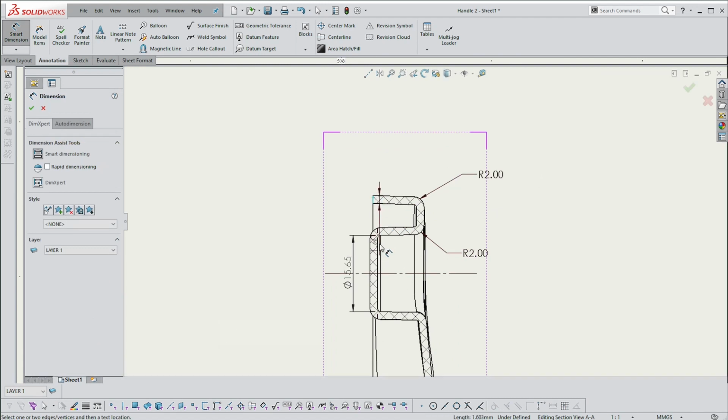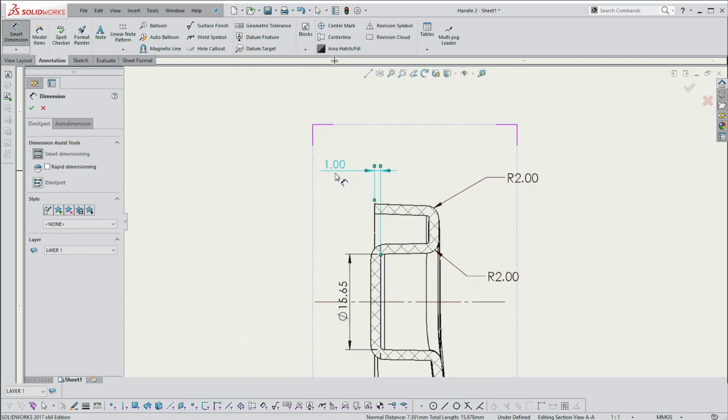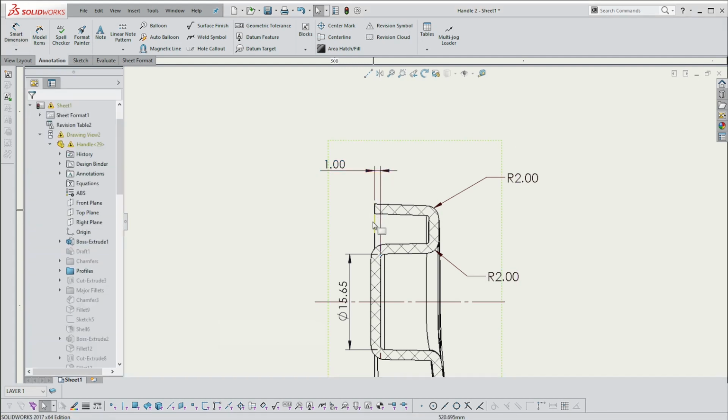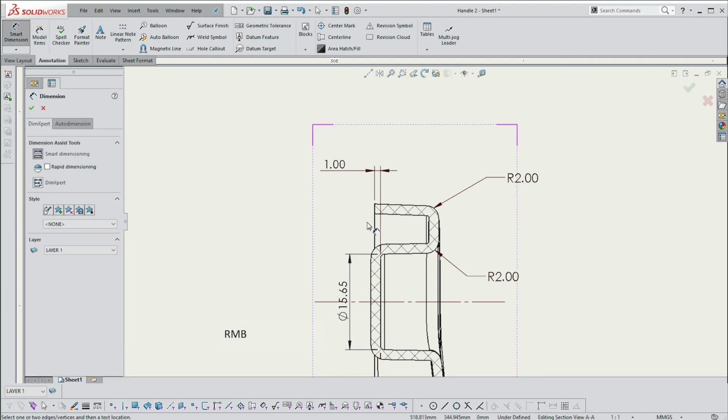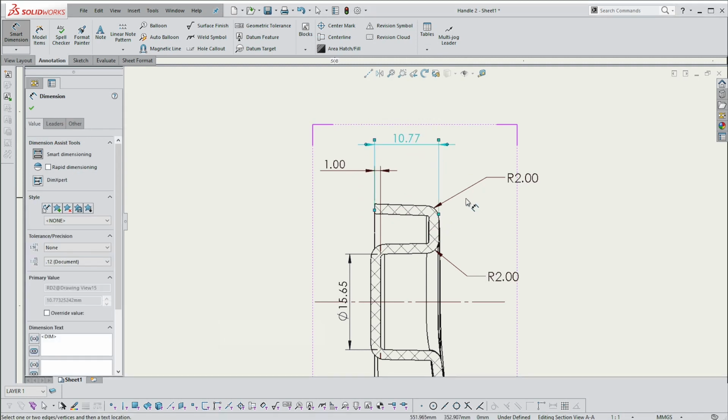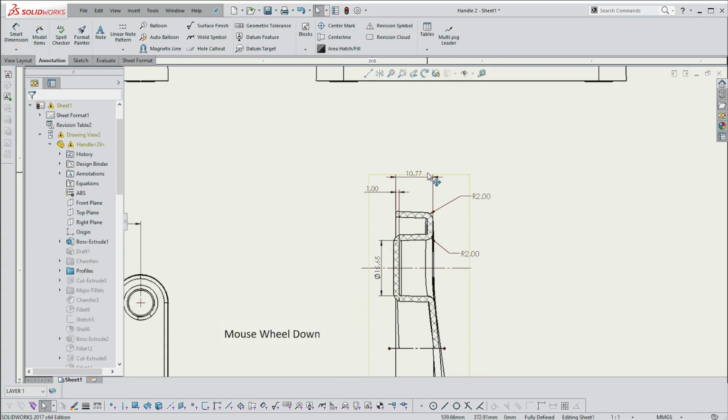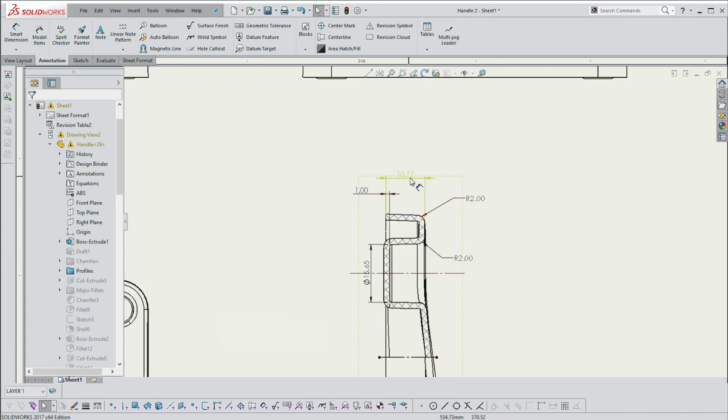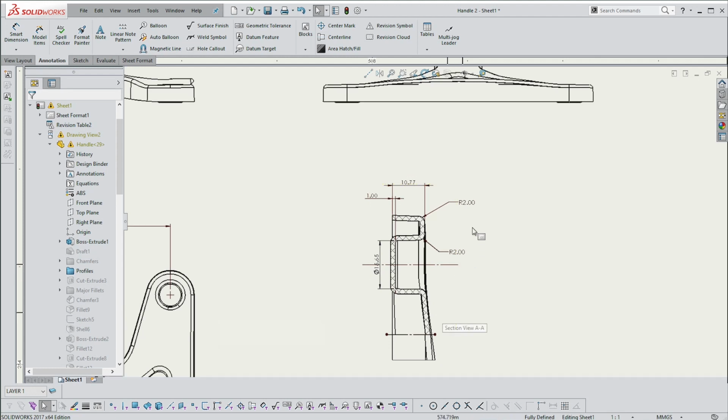are this height here. Remember that line there, or that plane, is a datum, so you must indicate all heights from that datum. So there to this one here. And if this were not as complex a model, that would round off to 11, but in this case, because it isn't, that's the best I can do. I'm not going to be too strict about that because it's quite a tricky model to dimension.